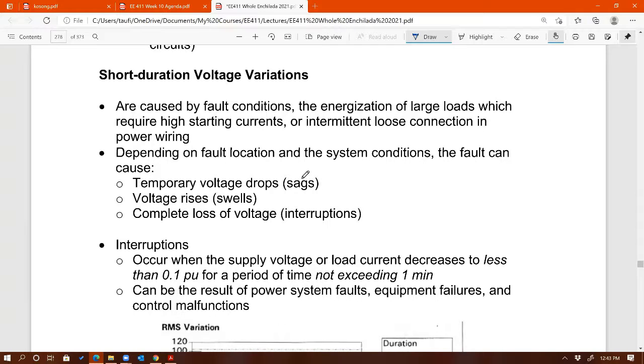And then same way, if you are running a three-phase induction motor, let's say for irrigation pumps, that would really depend on the horsepower of the pump. If the pump is tens of horsepower, that's big, and so no longer you're dealing with 30 amps, you're dealing with probably hundreds of amps at starting point. And that would drop the voltage easily on the distribution line. So it really depends on the size of the machines as well as the capacity of the electrical system. So hopefully that answers your question.